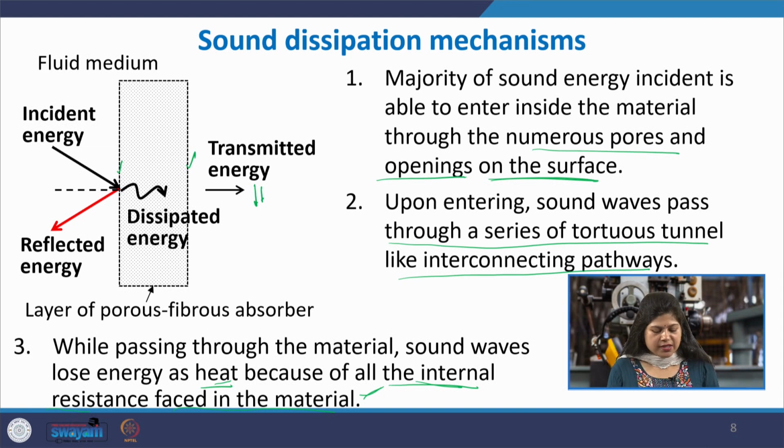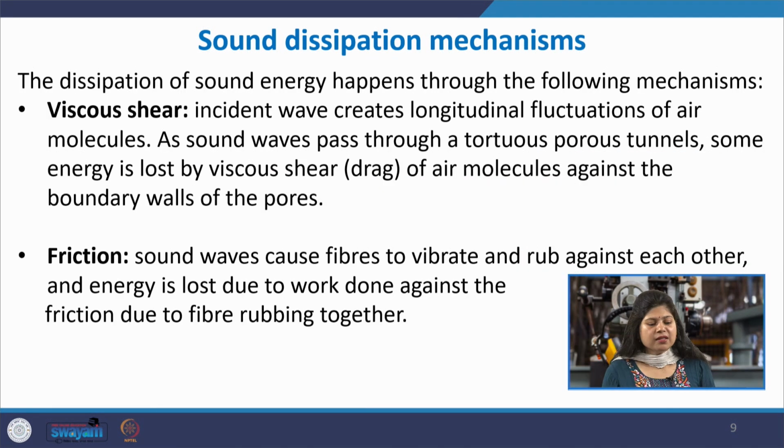What is the internal resistance that is faced? What leads to the loss of the sound energy as heat? The two most common phenomena that lead to the dissipation of sound energy in this material are viscous shear and friction. Experimental and empirical studies have shown that these are the most contributing phenomena. They have the most influence in dissipating the sound energy, although there are other phenomena as well.